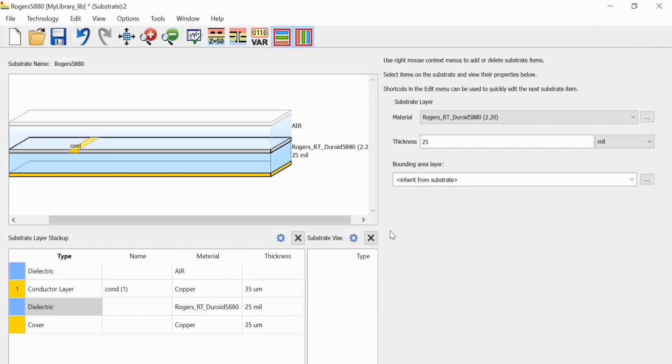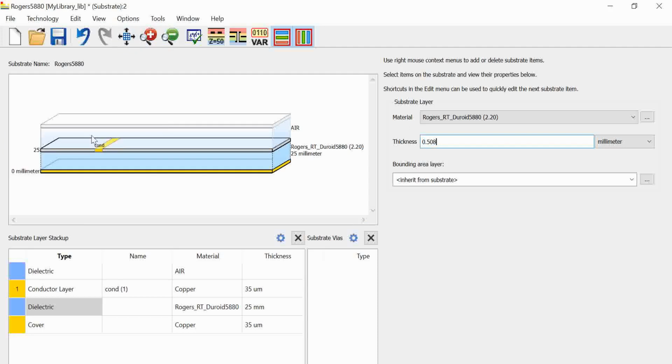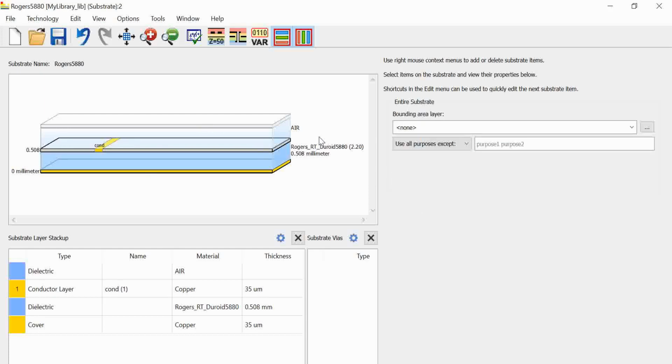Now press Ctrl+S, and wait a second, it does not have a proper dimension for the thickness. So the thickness which we are going to consider is 0.508, which is near about 20 mil, I guess, but I will use it in millimeter units. So that is my substrate now, Rogers RT/duroid, having this 0.508 millimeter thickness. And the conductor itself which we are using is copper anyway.